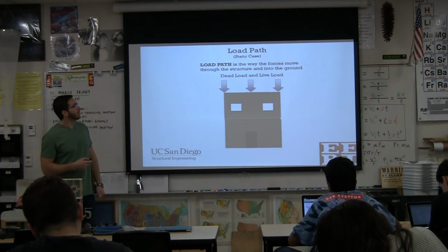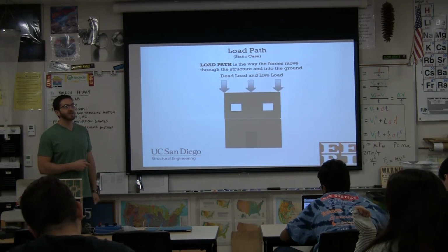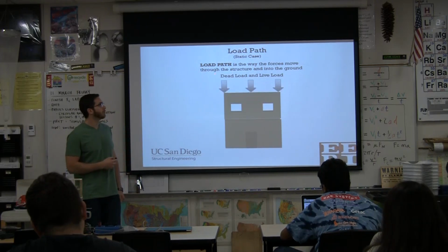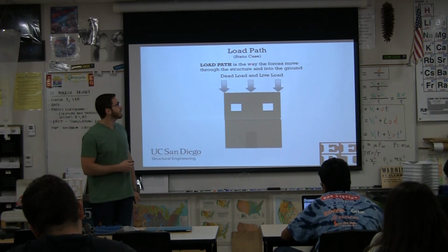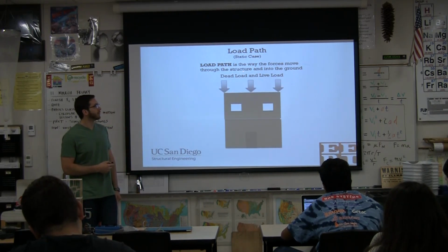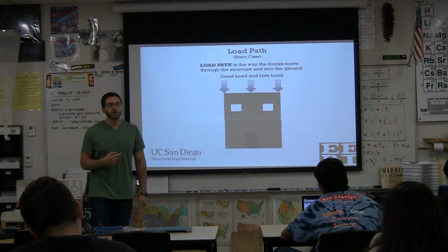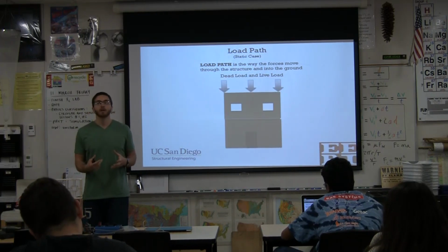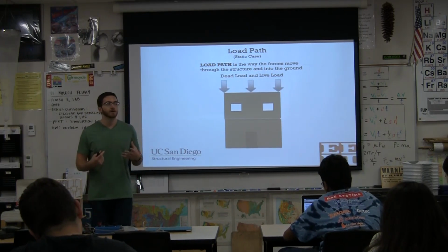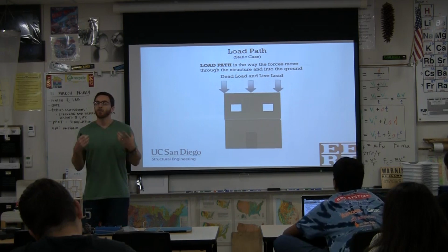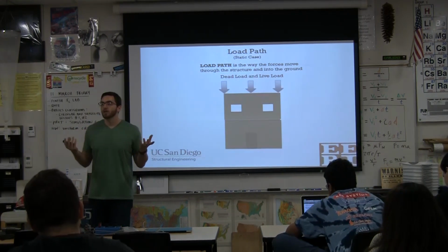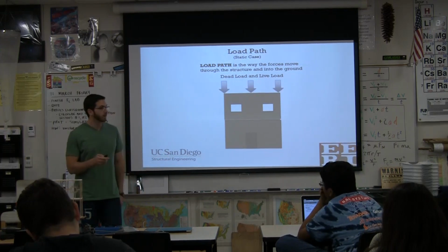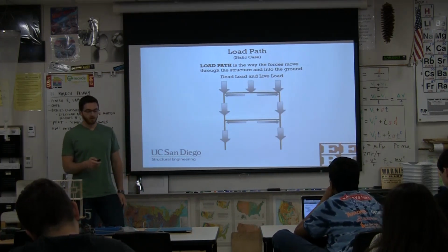All right. Load path. In a static case and the dynamic case, as structural engineers, we're focused on something called load path. The load path is the way forces move through the structure and into the ground. We talked about capacity and demand and how the capacity of each component needs to be greater than the demand for that component. The way you figure out what the demand is, is you follow the load path. Okay? It looks something like this.